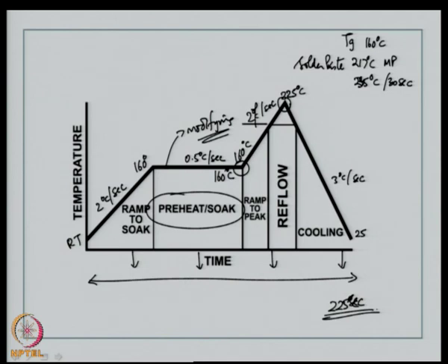So, the underlining point, the takeaway from these 2 slides that I have talked about is that there is no consistent thermal profile or a universal thermal profile. It depends on the system that you are using. So, look at all the issues carefully, look at the problem that you have in terms of components, substrate and paste, and then draw your own thermal profile, do a trial run 3 to 4 times on a board, look at the solder joint, examine the solder joint visually, and then go ahead if it is a mass production.